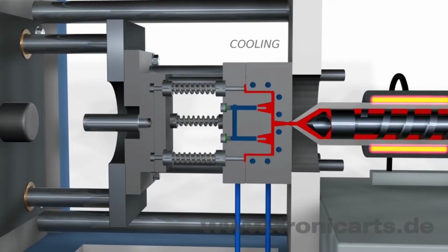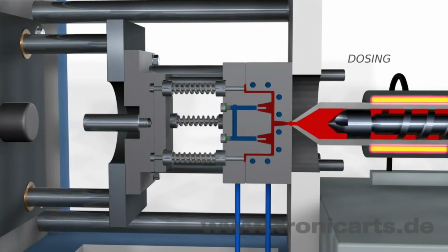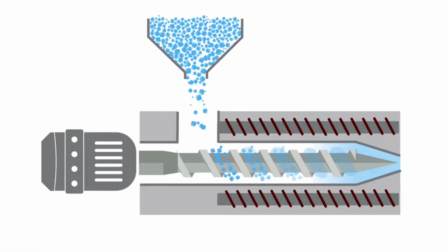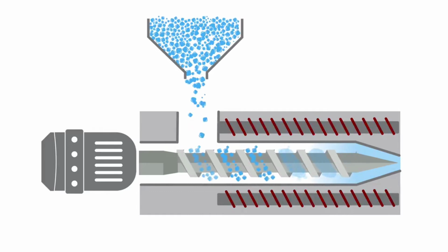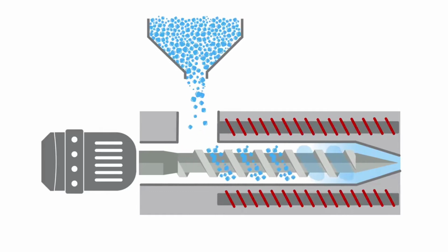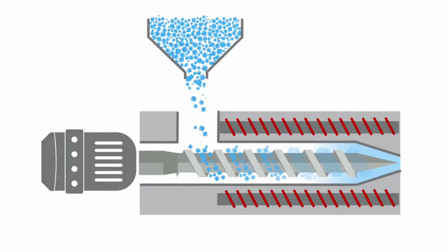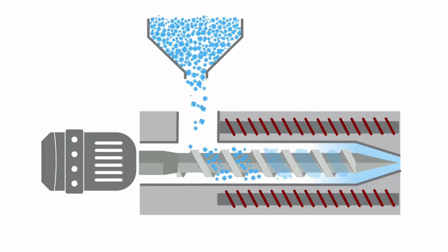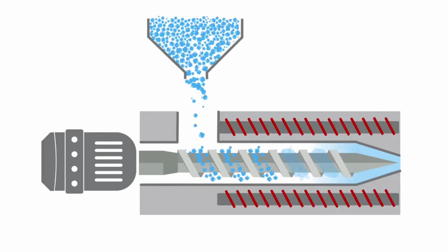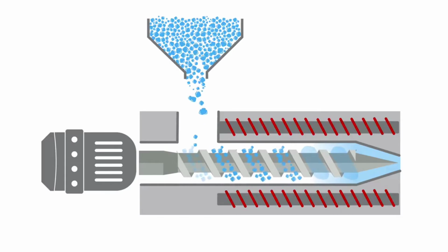Okay, by deformity I mean that when you produce your plastic, it will not have holes inside. In the extrusion process, it is similar, but here the materials are carried as shown. You can see as it's rotating, it's carrying the granules. Friction will make it melt, and then it is used not to make a mold, but most times to cover materials. For example, wires are covered by this method.